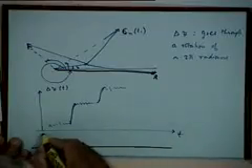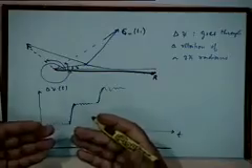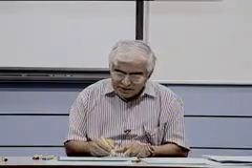Now, what happens to this is the phase demodulator output. What happens to the amplitude demodulator output? FM demodulator output. FM demodulator after all is obtained by passing the output of the phase demodulator through a differentiator. So the behavior that you will see will be more or less the same, except that it will be differentiated